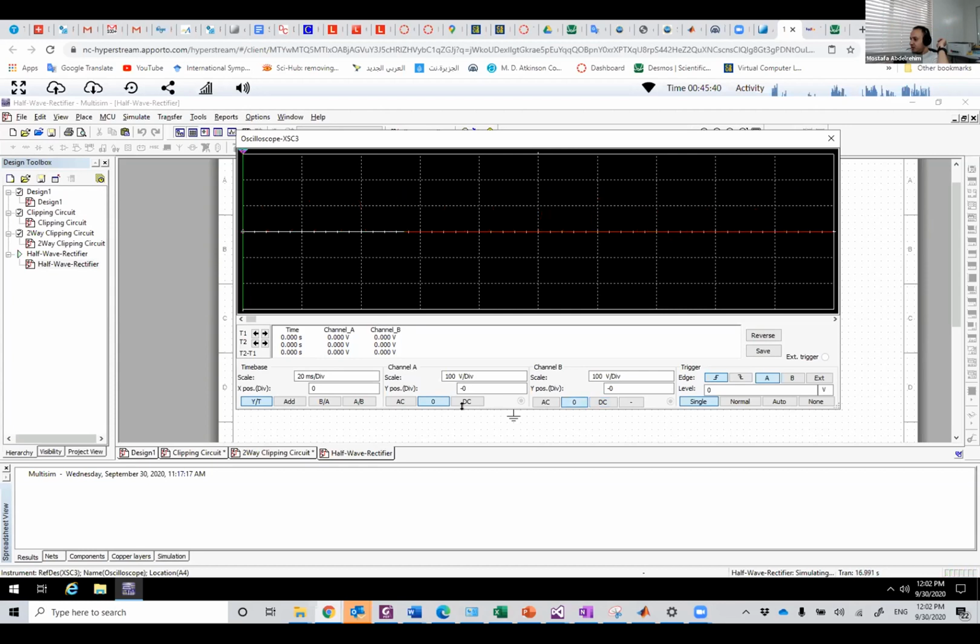This is the voltage on the diode. And you can't see the 0.7. If you go back to the analysis that I did, there should be a very small clipping at 0.7, but you can't see it, because now the voltage input is 110 RMS. It's 110 times square root of 2. It's 155.5. Very high compared to 0.7. So we can barely see this point. We can't see it actually.